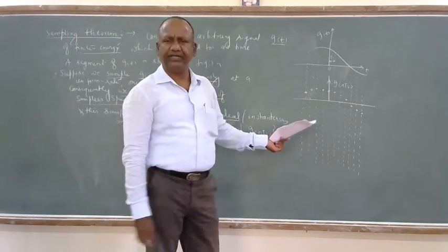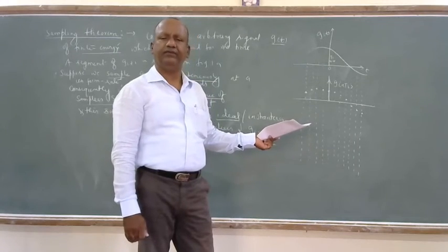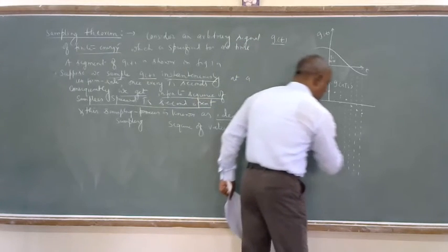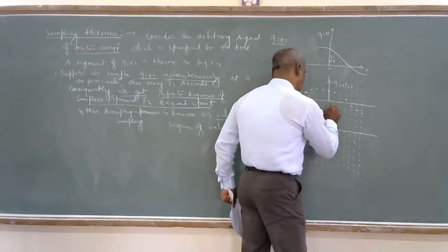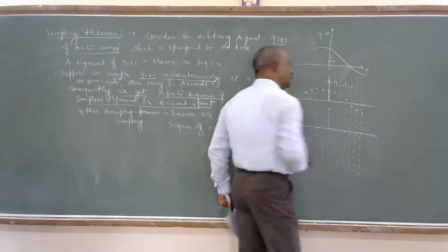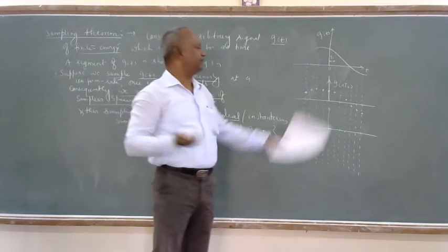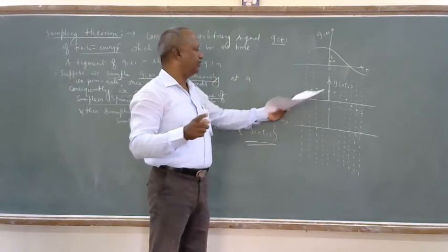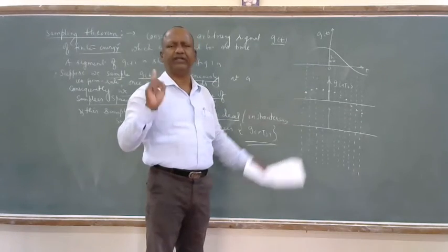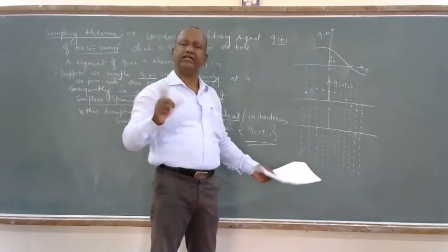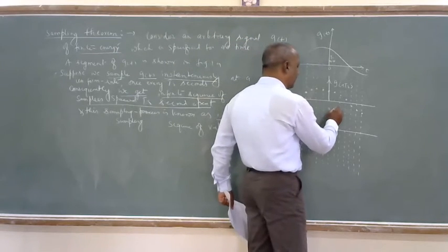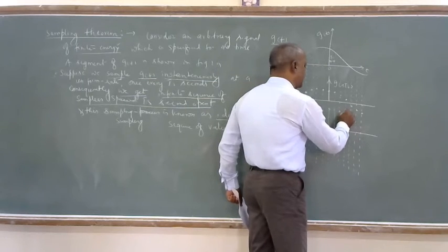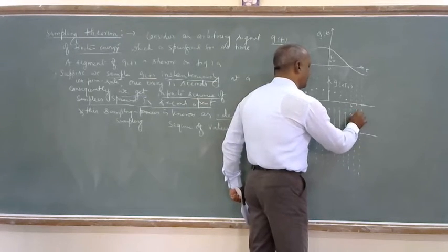But as a part of communication, I have to represent this in the form of a signal. So for that purpose, I am using the delta function, because the delta function does not affect the value. Delta function means the area under that function is equal to 1. 1 into this value means it is going to become that value itself. But that value is then available as a signal. So I am using a sequence of delta functions uniformly spaced at the rate of fs.